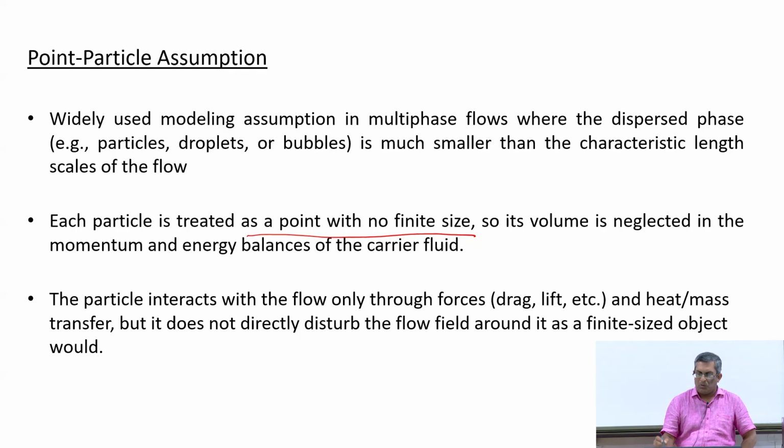So here you need to account for the force exerted by the particle on the fluid and also by the fluid on the particle. But if the particle size is very small, or if you assume that it does not occupy any space to create such phenomena, then your modeling assumption simplifies the problem. So, in that case, you can consider that I have only the drag term present and only the gravity term present.